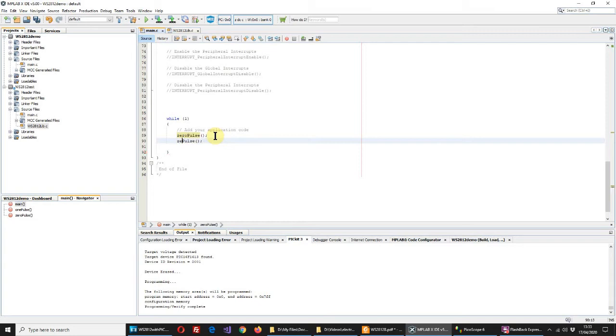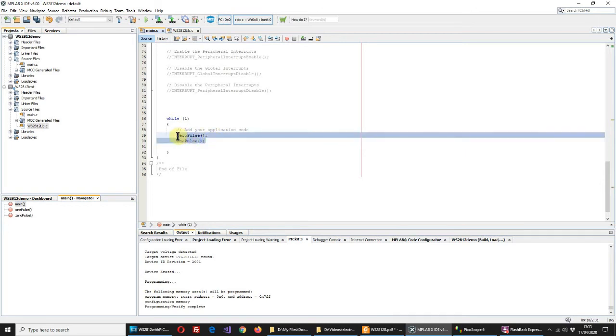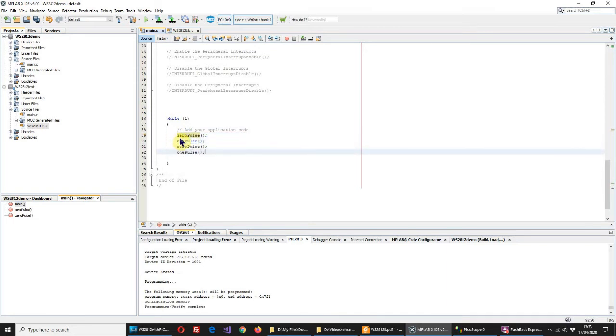Let's just change that. We have a 1 pulse in there, and let's actually copy that again and do 2 of each in our loop here, and then I'm going to follow that with a delay, just a small delay, so that we can see the actual spacing between them.